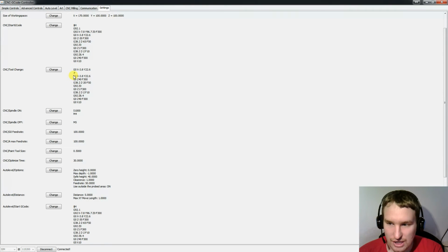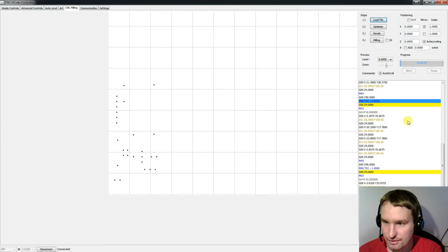And then if it's changed, I just tell it, okay, this happened and don't care about it. So I say, okay, continue. And then it's running the homing for this milling bit again, so it's referenced to the 0 position. And then the script is making the drill holes.